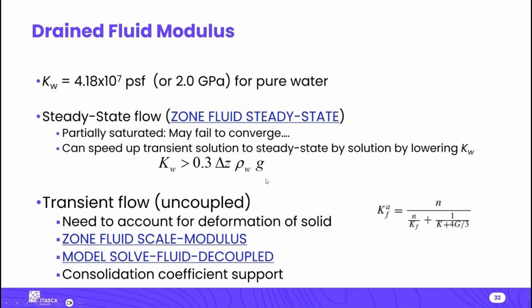In this case, the modulus is important, right? We can't just use this hacky number here to get to the steady state quickly. We need a realistic fluid modulus so that we get the right pore pressures at the right time.